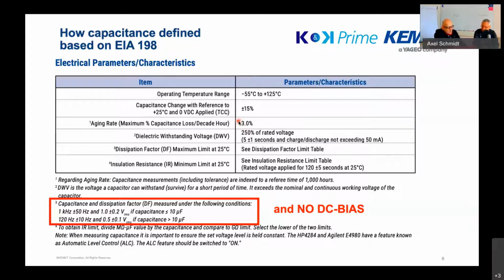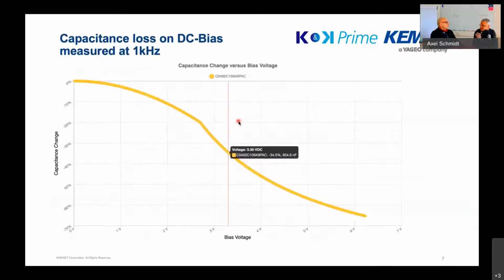As you probably know from the regulator two slides earlier, 500 millivolt or 1 volt ripple on a 3.3 or 2.3 or 5 volt system is way too high. Nobody can live with that. And the question is, what happens if the ripple is only 25 millivolt or 100 millivolt, as in typical application values? And with DC bias, of course.